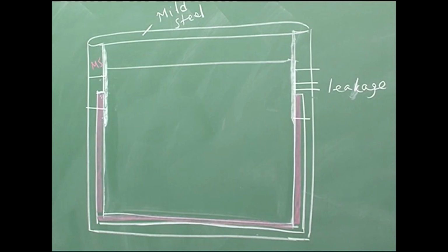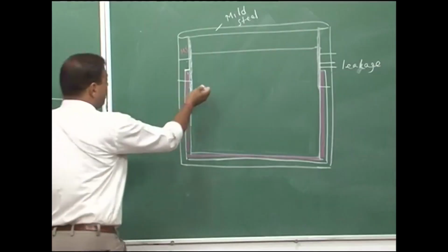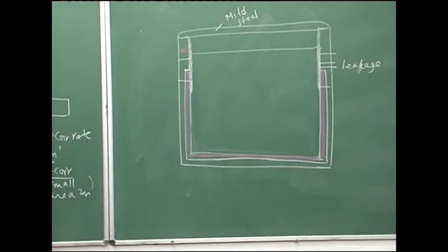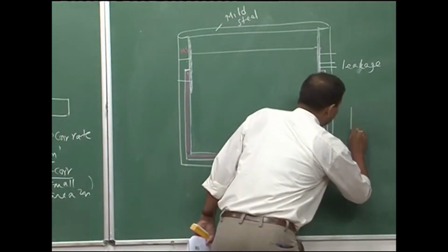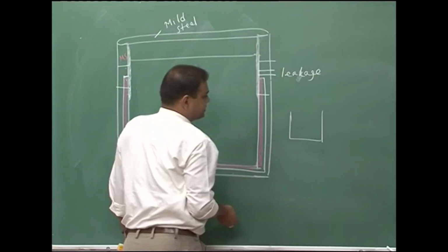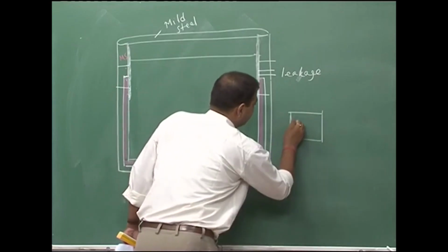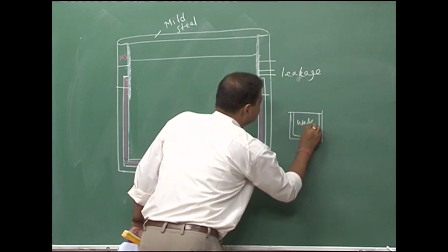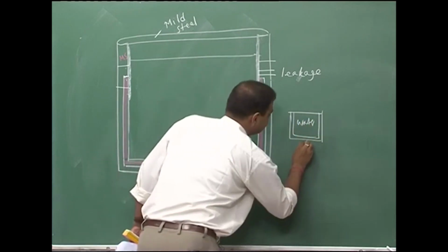The main point is whether the situation is due to corrosives, dissolved oxygen level, or heavily corrosive action. So, we can do one experiment. We put mild steel and stainless steel in a stainless steel container, put the same water, and then boil it.